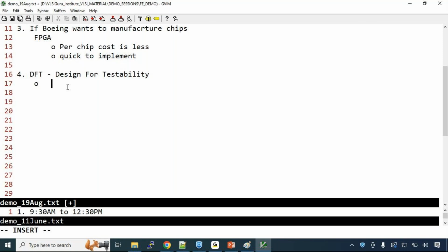Before that itself, we have the chip. Actually, during chip manufacturing, we are manufacturing at 5 nanometer technology. What is 5 nanometer technology? It is the transistor channel length. The distance between drain and the source is called channel length. 5 nanometer is a very small length, right? It's very difficult to even imagine that small a thing. I can imagine 1 centimeter is this much. How do I imagine 5 nanometer? It's so small. When you manufacture at that level, there can be manufacturing defects.